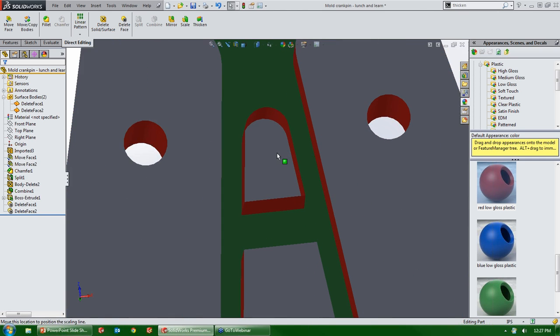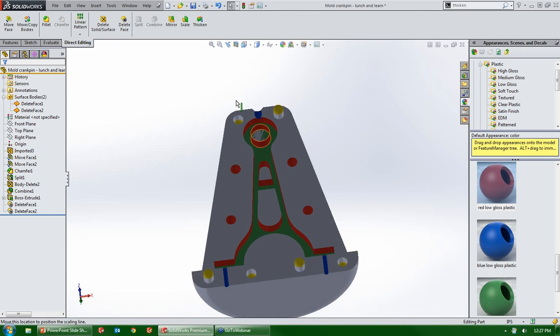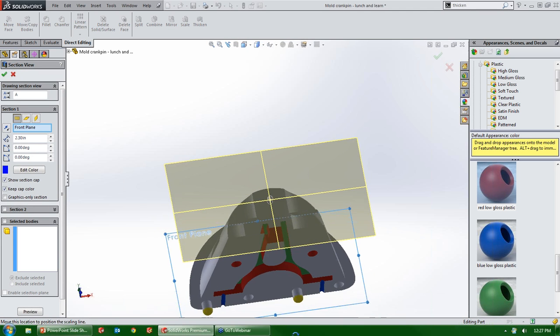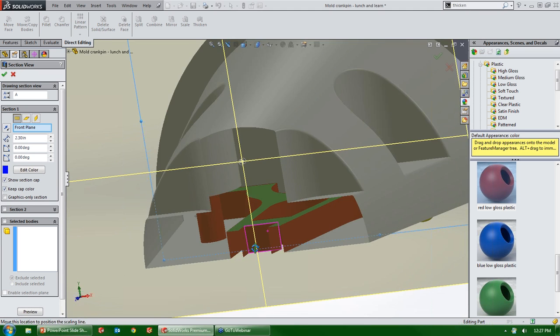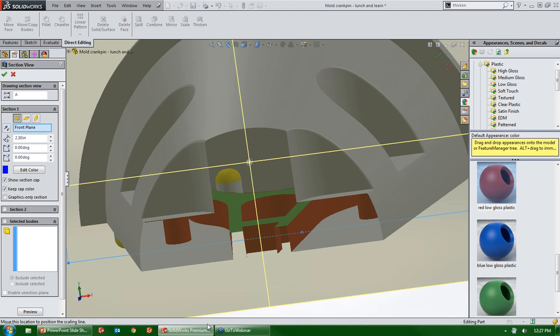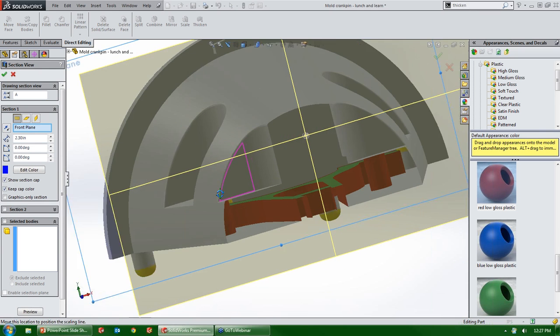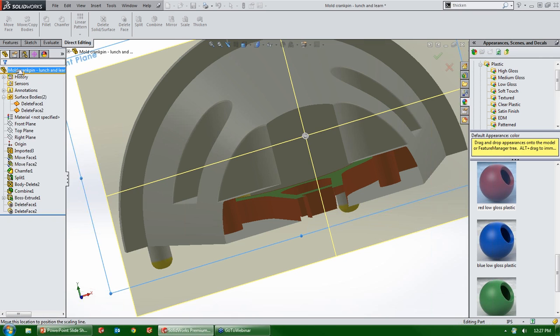You'll notice that I have a second body. So what I did was turn everything internal to this mold into a surface. So if you're doing surfacing, this is a quick way to create a solid model, delete a face from it, and have a full surface body that you can start to edit and manipulate.